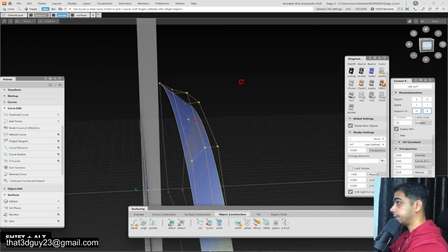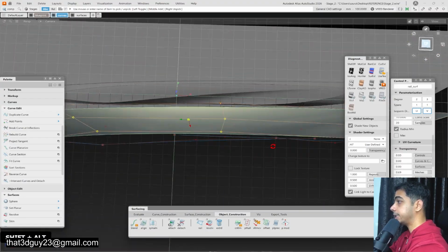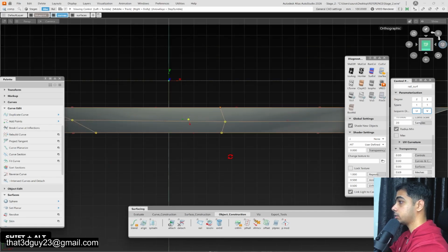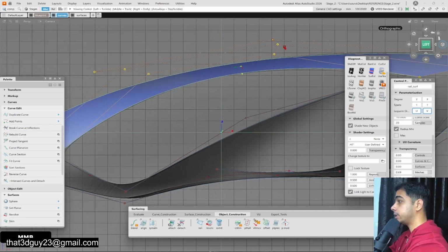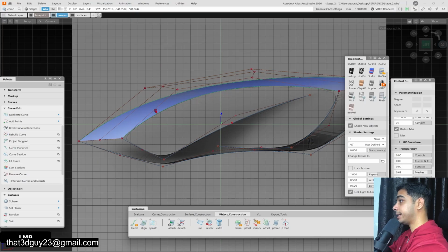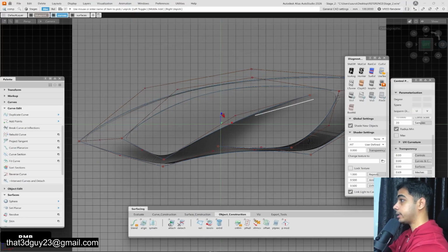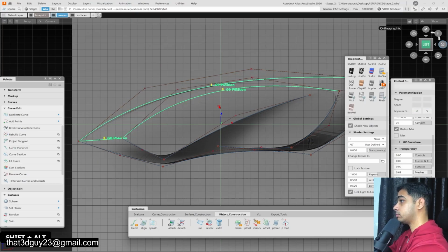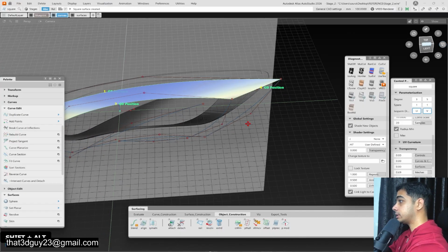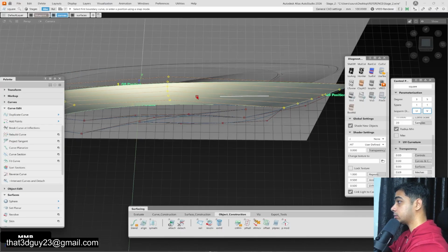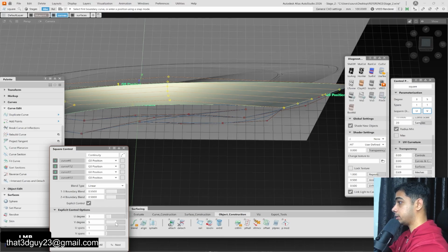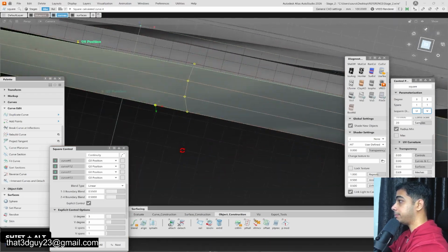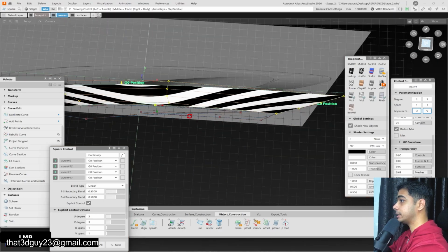Yeah, looks okay. I think I might change it if I feel like it, but for now it's okay. Why I'm using bi-rail instead of square: what square would have done is obviously give us something similar, but when the complexity changes, it flattens it out a bit more.